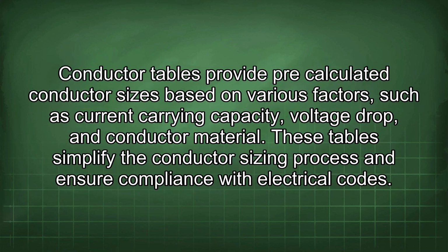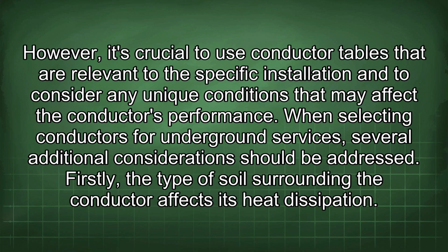Conductor tables provide pre-calculated conductor sizes based on various factors such as current carrying capacity, voltage drop, and conductor material. These tables simplify the conductor sizing process and ensure compliance with electrical codes. However, it's crucial to use conductor tables that are relevant to the specific installation and to consider any unique conditions that may affect the conductor's performance.